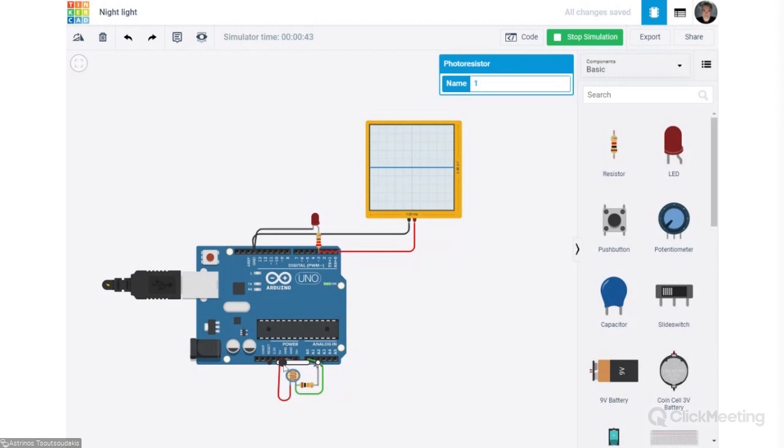Just to explain this a little bit, for example, in a period of 10 seconds, I have 5 pulses of 5 volts that last only 1 second each. That means that we have a mean voltage of 2.5 volts.